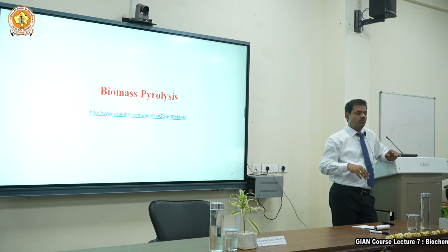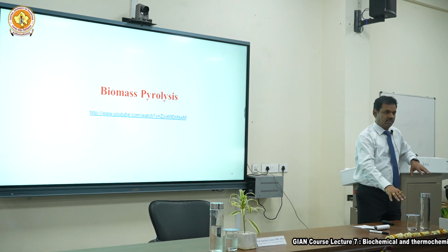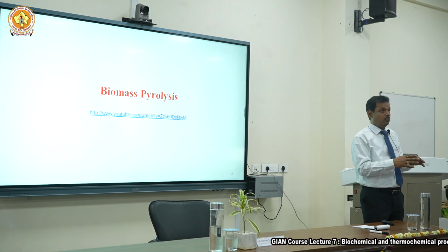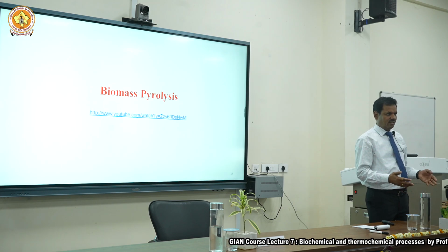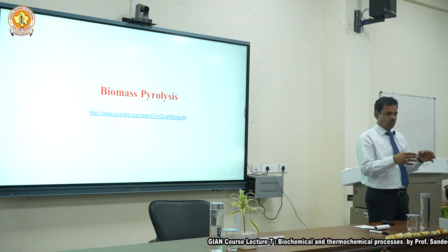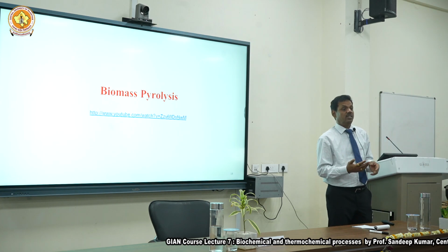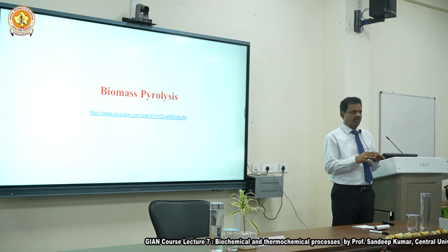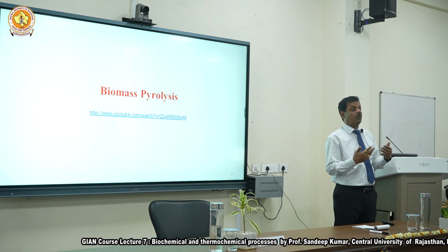When you cool it down, what will happen? You try to go back. There are so many reactive species inside this gas and they are trying to go either gas or liquid, or gas or solid, but in the end they will start joining because of chemistry or radicals. When they join together and you cool it, they drop, and it becomes tar or oil. Right? So that's how you get oil formation.